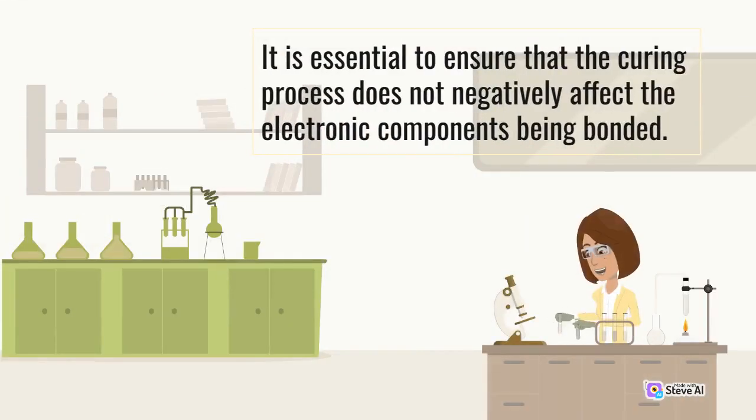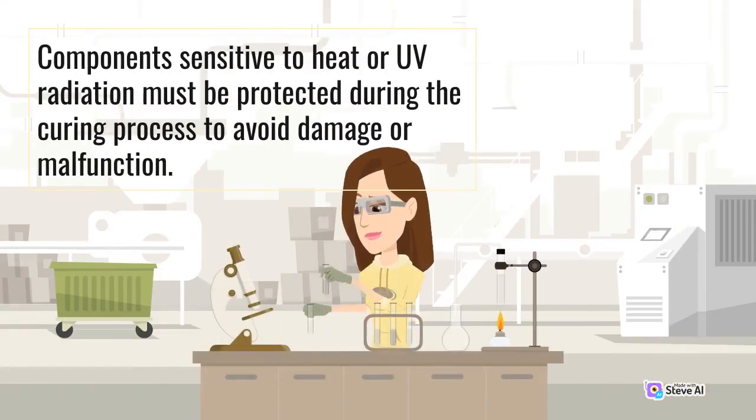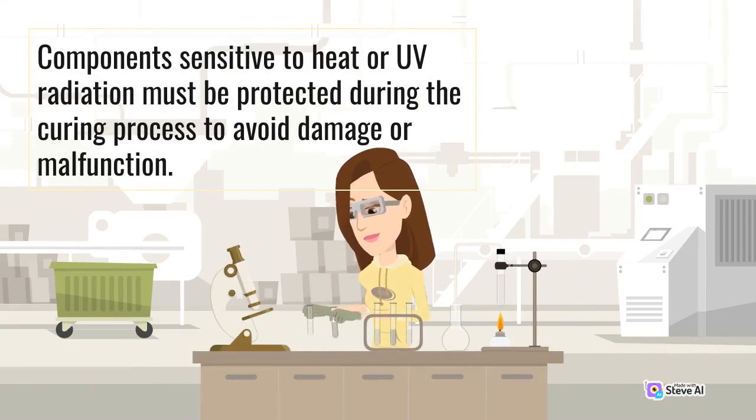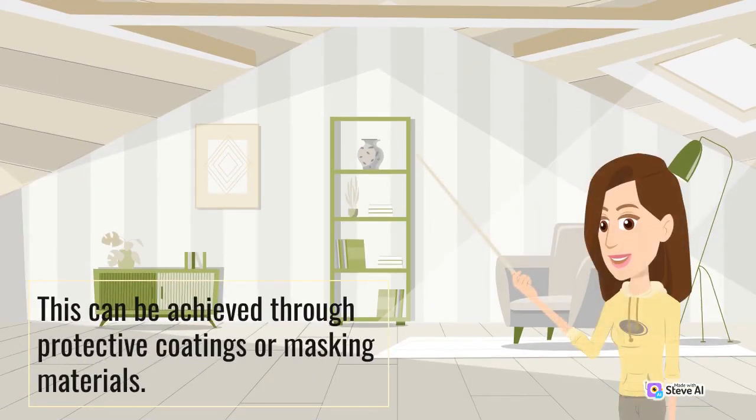It is essential to ensure that the curing process does not negatively affect the electronic components being bonded. Components sensitive to heat or UV radiation must be protected during the curing process to avoid damage or malfunction. This can be achieved through protective coatings or masking materials.